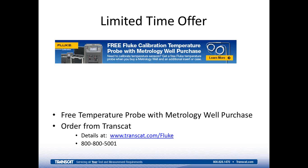And as I mentioned before, on any good calibration report, it should tell you what the proportional band was when the unit was calibrated. It's always best practice, if you don't do a bunch of testing to figure it out, to set it at that value unless you're doing something special.